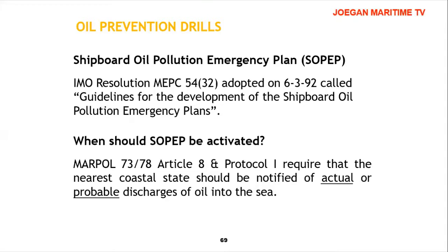Shipboard Oil Pollution Emergency Plans, or SOPEP. This was implemented by IMO Resolution MEPC.54(32), adopted in 1992, called Guidelines for the Development of Shipboard Oil Pollution Emergency Plans. MARPOL 73/78 Article 8 and Protocol 1 require that the nearest coastal state should be notified of actual or probable discharges of oil into the sea.